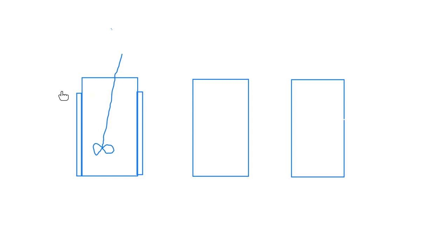As the mass increases, the volume increases to the cube, and therefore the heat of reaction, the number of kilowatts of exothermic heat, increases to the cube of the dimension, while the cooling area increases to the square of the dimension. So that is something to keep in mind.